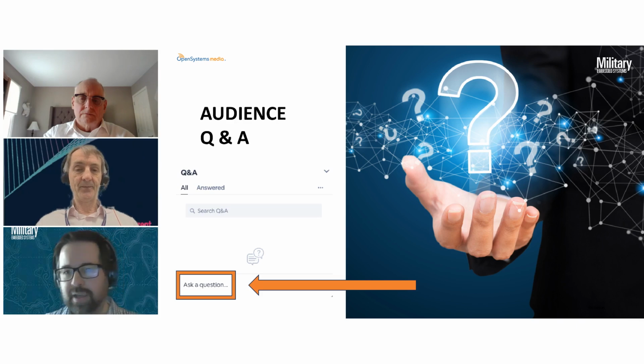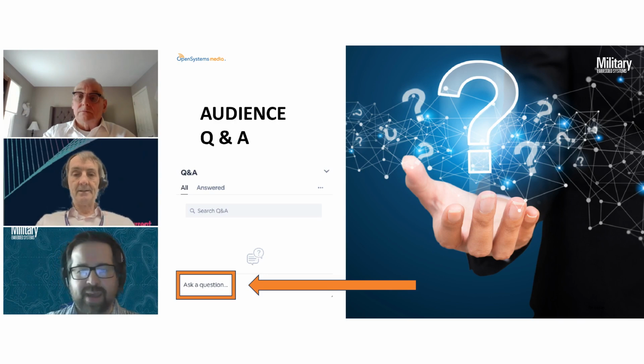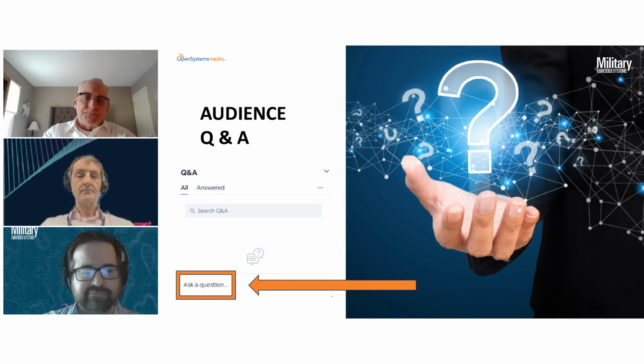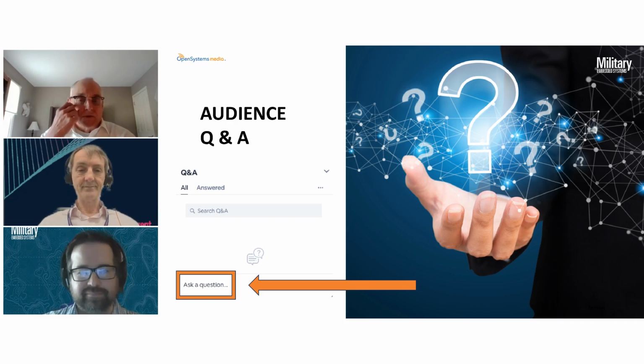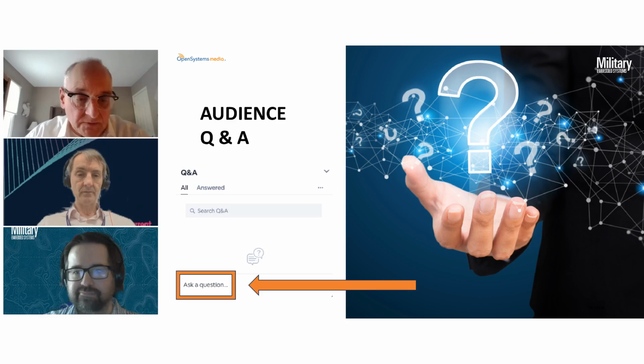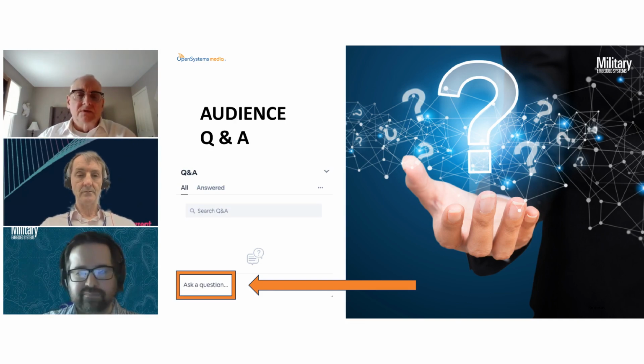Great, thank you. And Ken, what SBCs would support the AI backplanes? Nigel pointed out there's quite a few, but we've been focusing and doing a lot of our interoperability testing with single board computers that are available from Concurrent. There are two profiles: the compute intensive primary profile and the secondary profile. Concurrent's offering products that address both of them. One will give you x4 and x8, and the other will give you up to x16 to be able to make this implementation.